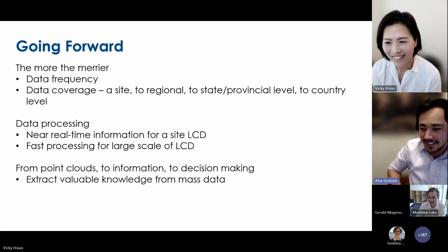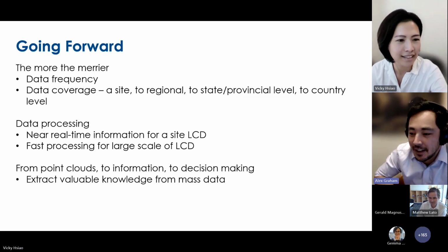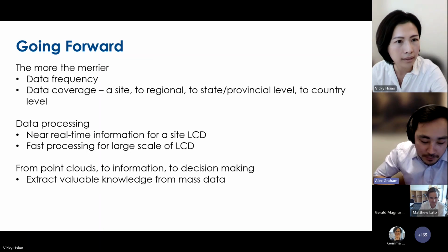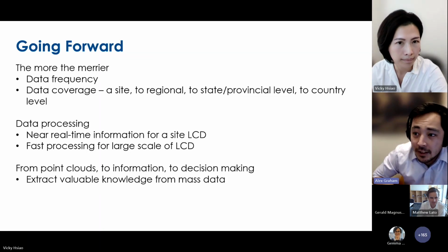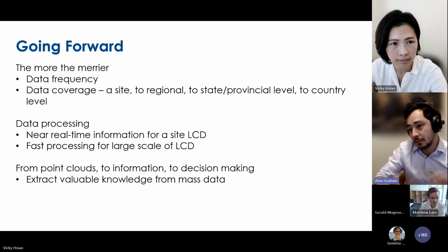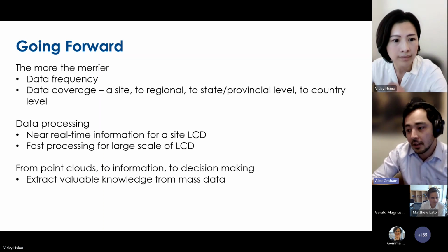All right, thanks, Terry. Yeah, I can take that one. So the chat was loading for me. Yeah, so like I said, if we want to achieve that alignment, we do need the point clouds. We can always do change detection on gridded DEMs, though there are some caveats to how precise the results are going to be.